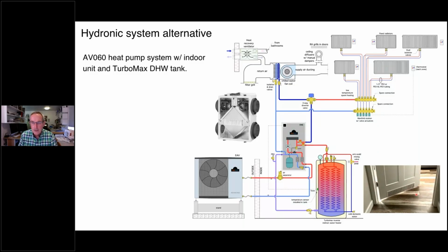That's a nominal 4 to 5 ton air to water heat pump system. And that system includes the outdoor unit. Over here, you see the monoblock outdoor unit, the indoor unit, which houses the circulator, the valves, the controls, the expansion tank, the auxiliary heater, and so forth.